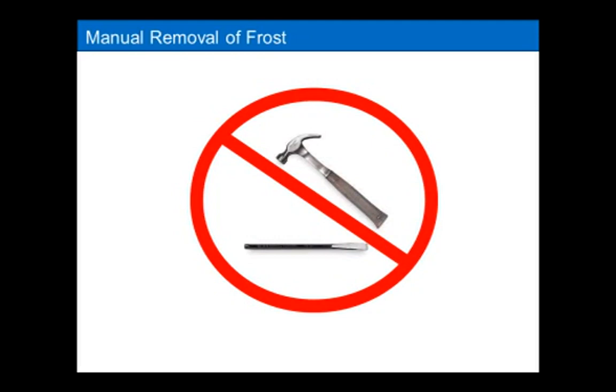Avoid using a torch. A torch is not recommended for defrosting an evaporator. It's not a controlled heat source. It will cause you more problems than good. A heat gun generally works pretty well.